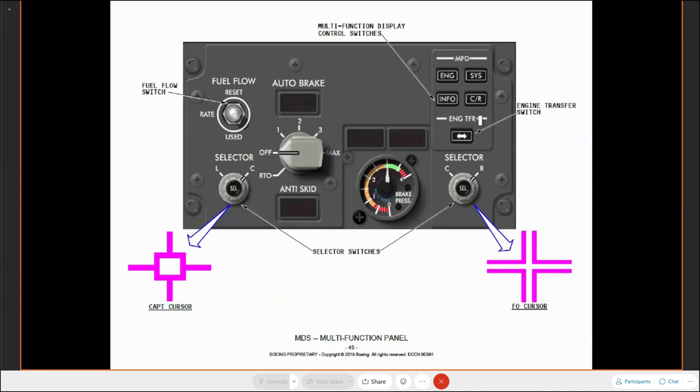If you take the option of having a Cat 3B aircraft, then you'll have this cancel recall switch. It allows me to cancel and recall advisory messages for Cat 3. Okay, cancel recall, those Cat 3 messages, if you have the option, are shown on the engine page, and I'll show you where they are when we get to it.